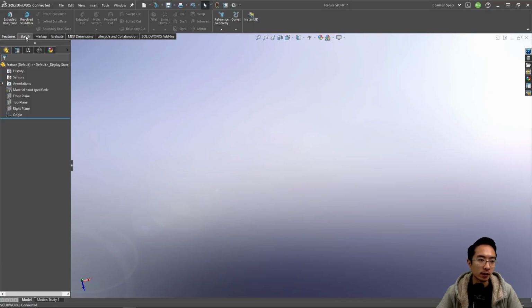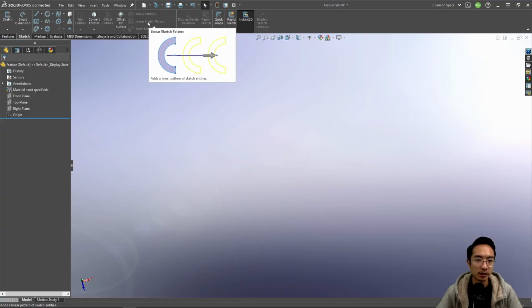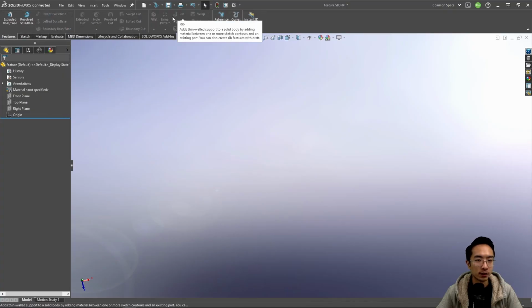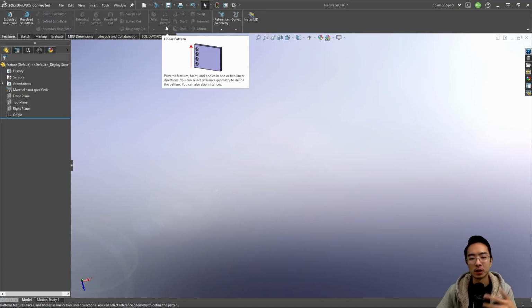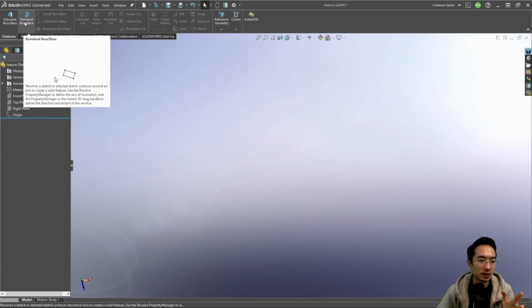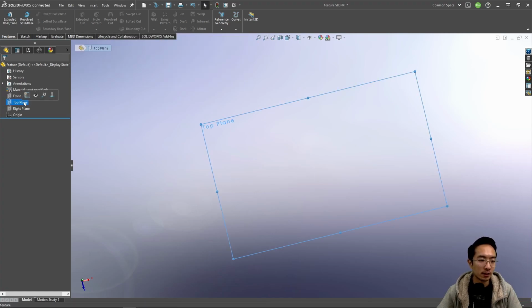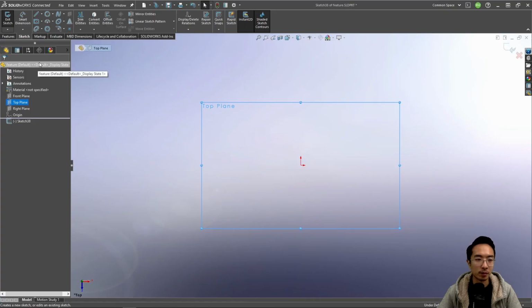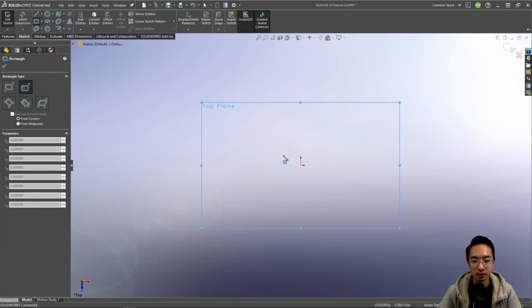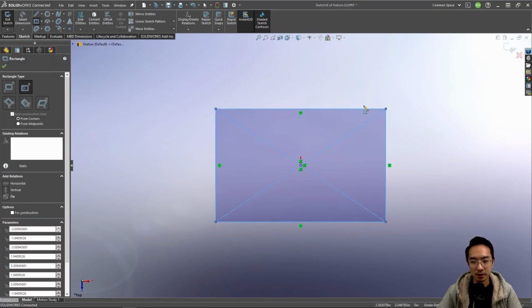Okay, so in this video, we're going to talk about the feature patterns that we have in SolidWorks. As you recall, in the sketch we had sketch patterns for features. It's a way to repeat any of these features that you've made. So if it's a boss or a cut, you could repeat that in different patterns. So it's good for anything that has any sort of pattern associated with it. A lot of times it's for cutouts, or maybe you have something with a lot of bumps as a pattern, you could do that as well.